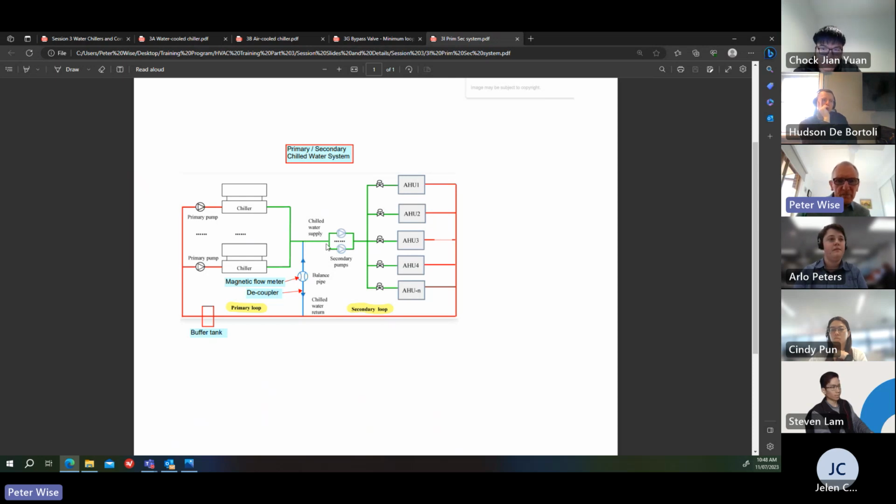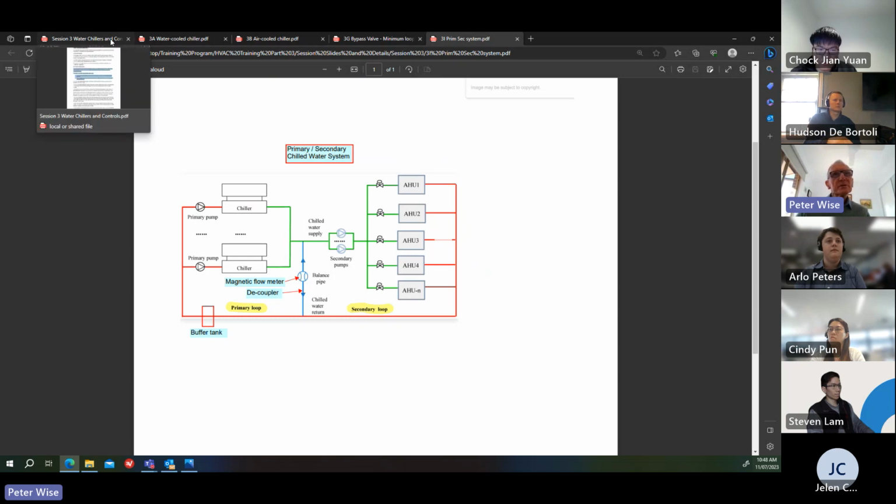And your control system will then pick up on that. I don't want to go through the controls in detail because we'll be here all day, but it'll pick up that there's a flow in the negative direction and the temperature in the field is increasing. And then it says, well, we need more chilled water capacity. So that's part of the staging strategy as well. The concept is simple, but achieving it with the controls is not always as simple.